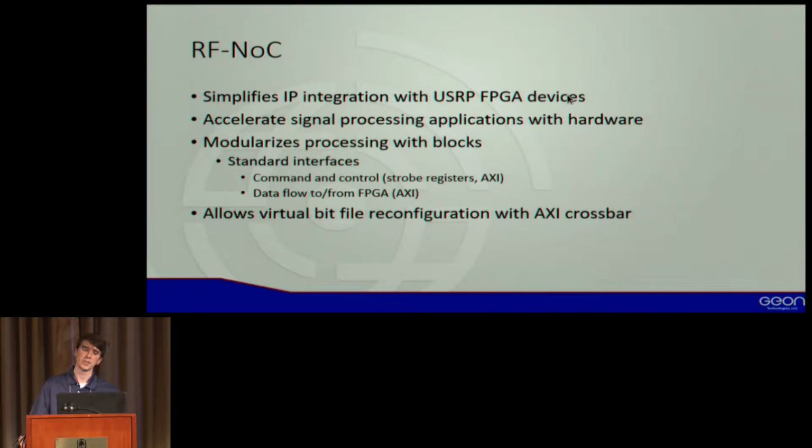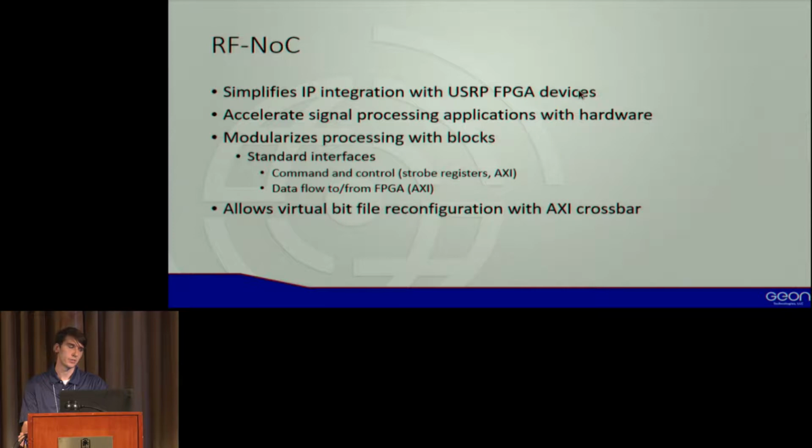So if you have an IP from a vendor or from an open source repository or something you developed in-house, whether it's in Verilog or VHDL, you can wrap it in these standard interfaces. A different developer can do the same thing in a vacuum, and then ideally, you can integrate with zero cost. Another really important part is the ability to connect your blocks together after the bit file has been loaded and in different configurations. So then, without reloading your bit file, you can get different behavior. If you have blocks A, B, and C in a bit file, you can connect blocks A and B, push some data through, get one behavior, disconnect those blocks, connect blocks B and C, push the same data through, and get a different behavior.